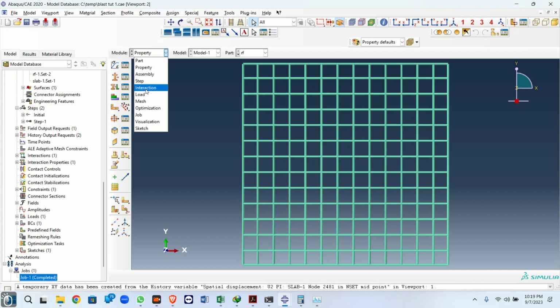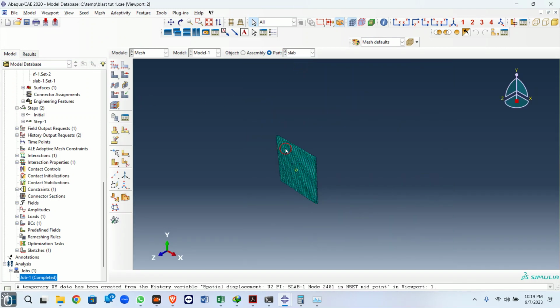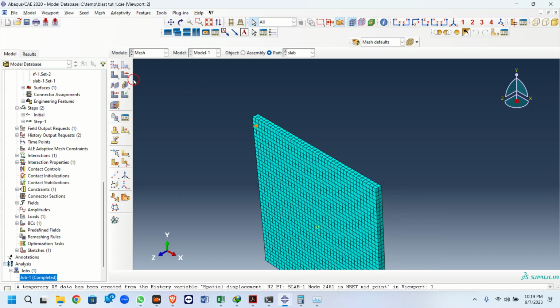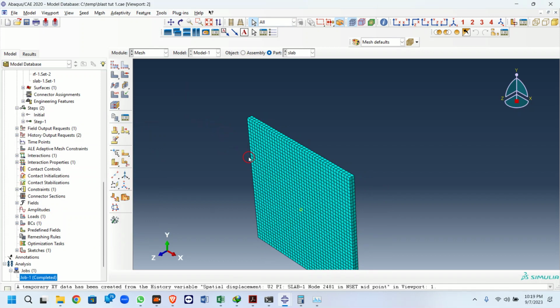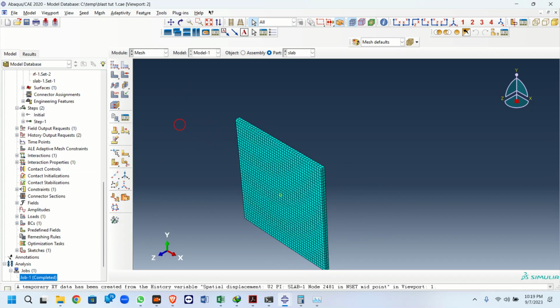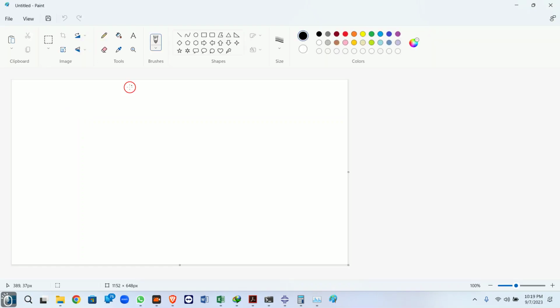Second uncertainty is the meshing. So for meshing you have to perform the mesh convergence study. You can't say that the mesh size that I have used, 25, is correct or 10 is correct. What you have to do is a mesh convergence study. So the mesh size on which the result does not change. I hope you know the mesh convergence study. Not much. What we do in CFD, that study only you are talking about.